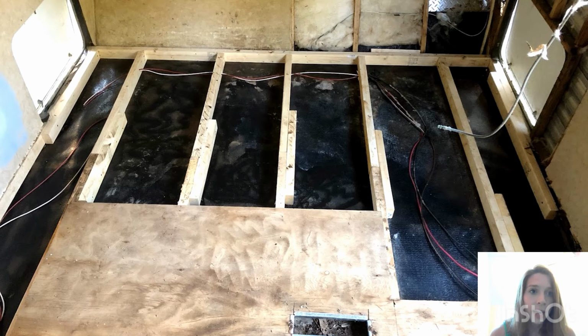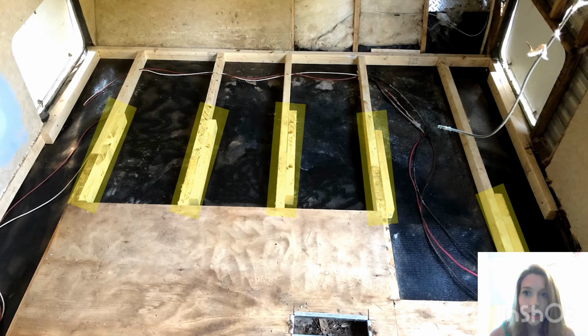If you look at the yellow highlighted areas, this is where I created a buddy joint that I was telling you guys about before, where my old joist will meet my new joist. So I use pocket holes to initially join the 2 pieces of wood, which are the areas in the arrows in white right there. And then I used a really long scrap piece of the same size to screw into the new and the old joist as additional support. So if you look at the arrows in green, that is where I put screws in to join that long piece from my old joist to my new joist.